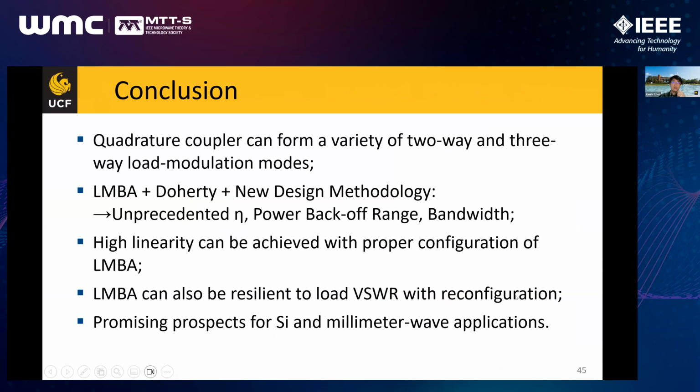So in conclusion, I introduced that the quarter coupler can form a variety of two-way and three-way load modulation modes as a unified load modulation platform. And then by combining LMBA with Doherty, with the new design methodology we introduced, it can achieve unprecedented efficiency, power backoff range, and especially almost unlimited bandwidth.